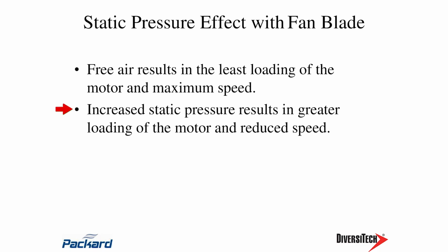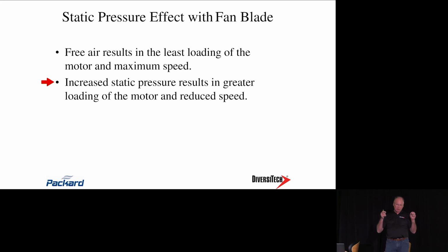And it does. So as I add static pressure to that, what does that do to the load? It increases the load. And if I have a PSC motor, what might that do to the speed of that motor as I add static?